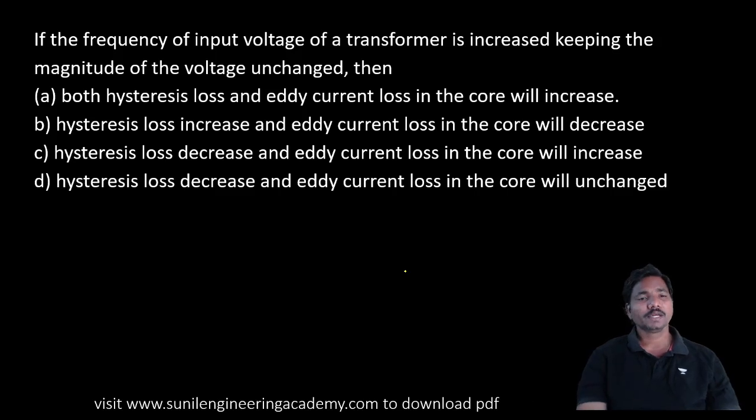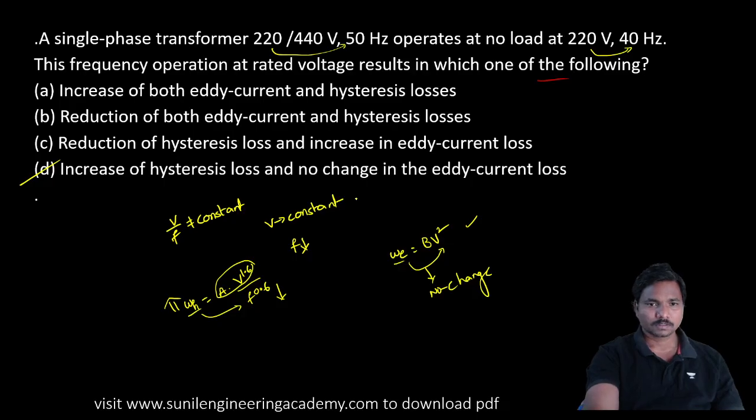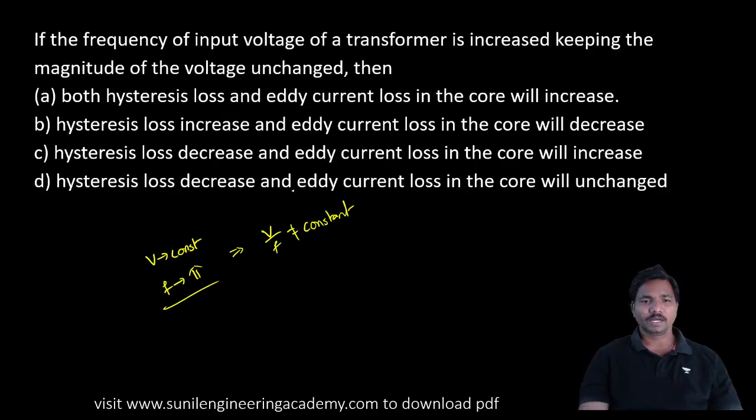Coming to the next one. If the frequency is increased by keeping the voltage constant, that means V by F is not constant. One is constant, one increases, so V by F is not constant. And V is constant. Then what about the hysteresis losses?